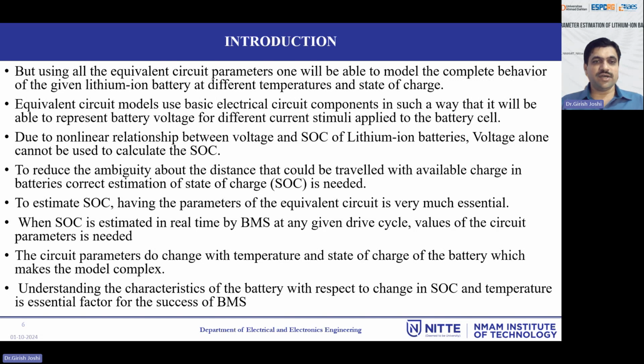Equivalent circuit models use basic electrical circuit components in such a way that they represent battery voltage for different current stimuli applied to the battery cell. Due to the nonlinear relationship between voltage and state of charge of lithium ion batteries, voltage alone cannot be used to calculate the SOC. To reduce the ambiguity about the distance that could be traveled with the available charge in the batteries, correct estimation of SOC is needed.